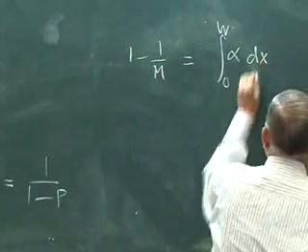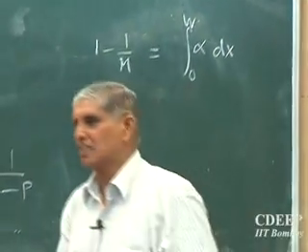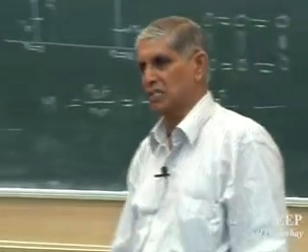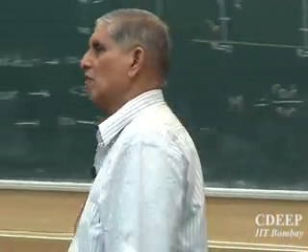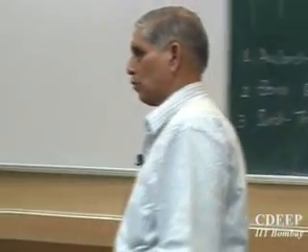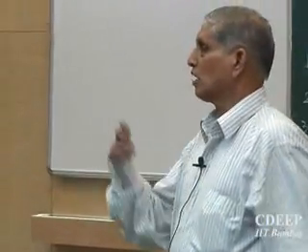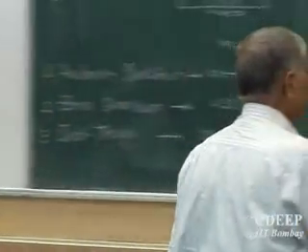Where alpha is called the ionization rate, the rate with which ionization takes place. Alpha n is the ionization rate for electrons, and alpha p is the ionization rate for holes. Ionization means breaking a bond. Right now we assume electrons and holes have the same ionization rate, alpha.